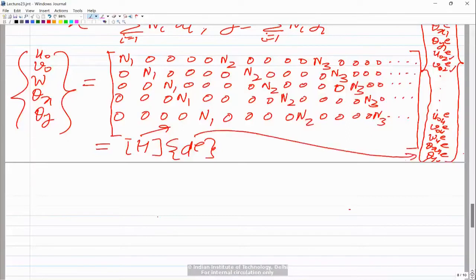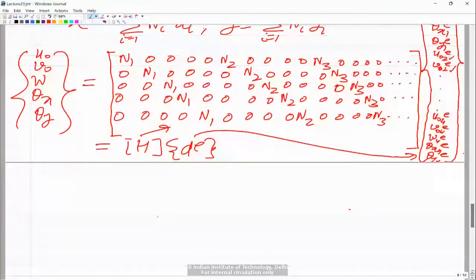So you would see that the formulation is more or less the same. The only thing is the number of unknowns is more. So you can formulate a 4-noded plate bending element, you can formulate an 8-noded plate bending element, you can formulate a 9-noded plate bending element, and so on in the same logic. So whatever interpolation we have been discussing so far, you could actually use the same logic to formulate this element.